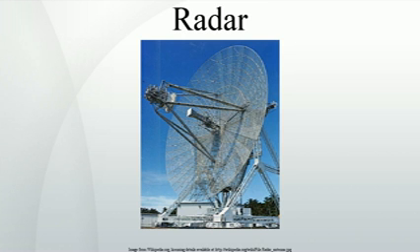Doppler shift depends upon whether the radar configuration is active or passive. Active radar transmits a signal that is reflected back to the receiver. Passive radar depends upon the object sending a signal to the receiver. The Doppler frequency shift for active radar is as follows, where f_D is Doppler frequency, f_T is transmit frequency, v_r is radial velocity, and c is the speed of light. Passive radar is applicable to electronic countermeasures and radio astronomy as follows.